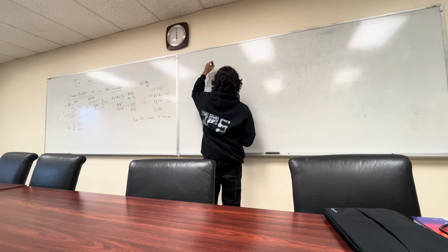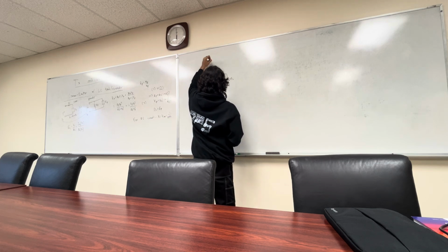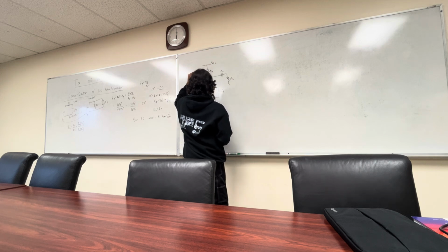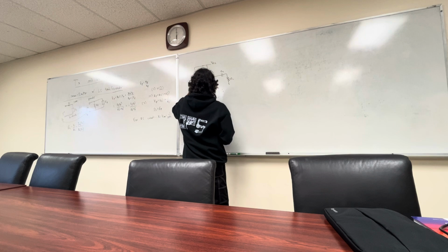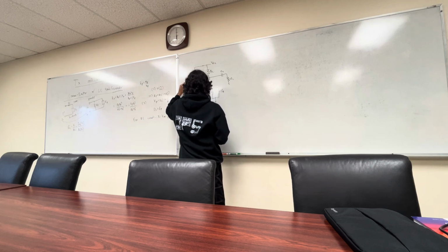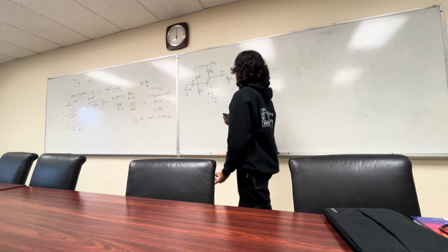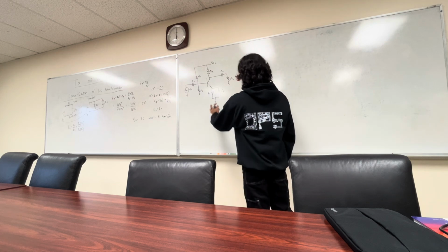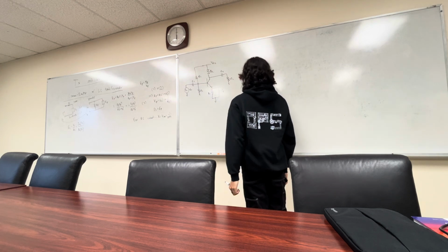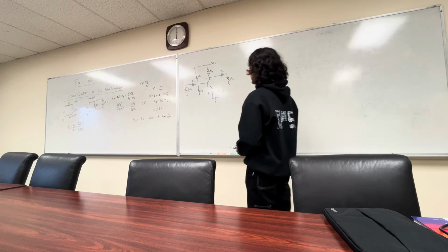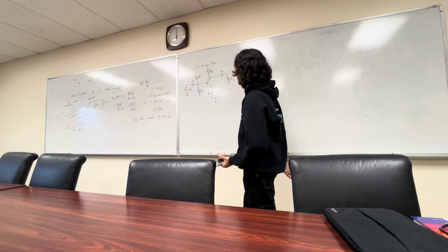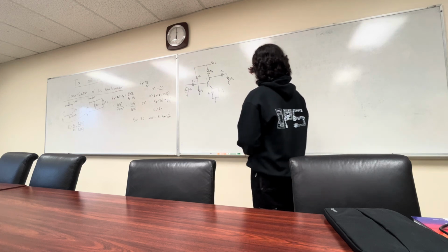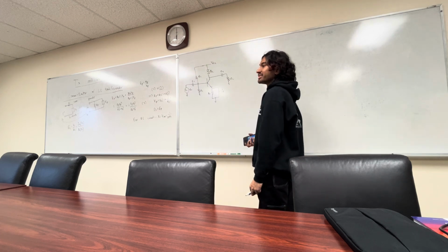Call this C2, RC. This is our basic common emitter amplifier with emitter degeneration and a bypass cap, and R1 and R2. There's RE here for better beta and temperature stability. Any questions on that? It kind of looks familiar.